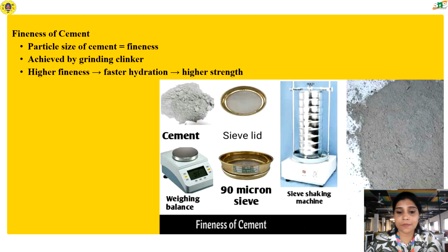Here comes the fineness of cement. Fineness refers to how fine or coarse the cement particles are. The smaller the particle size, the larger the surface area for hydration. Hydration is the chemical reaction between cement and water. I talked about hydration, and this reaction is what gives strength to concrete.